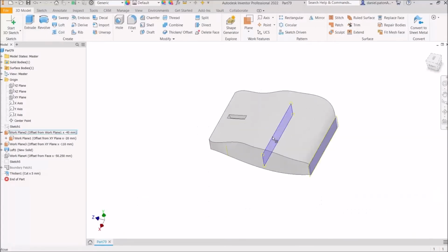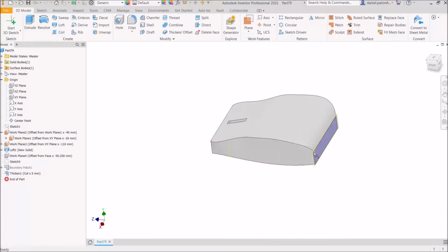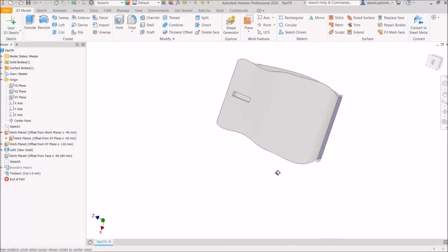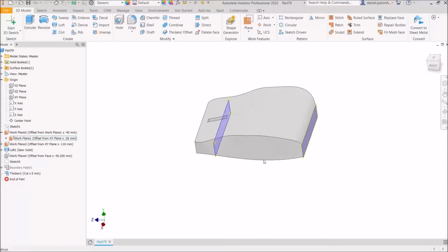That's not the only projection tool that we have. So let's say that we wanted to create some cutouts on the side here, for instance. Again, this is also a curved face. You can see nothing is straight on that face. It's all curved and going at different angles. So what we could do is we could start a sketch on, say, a side face somewhere.